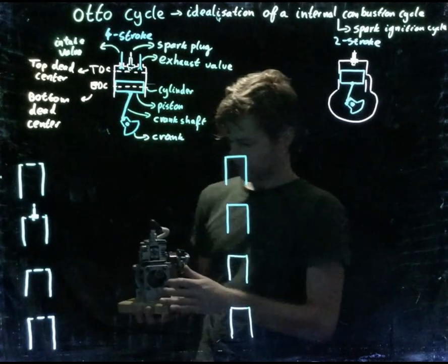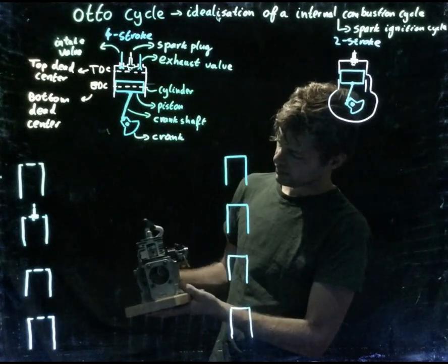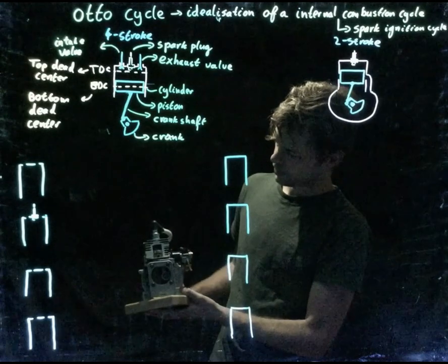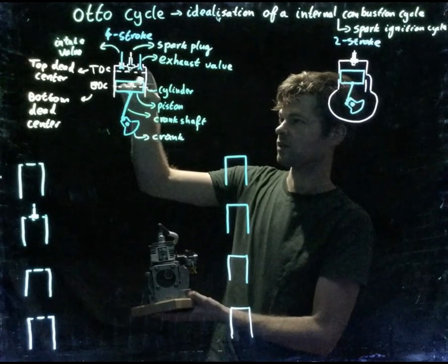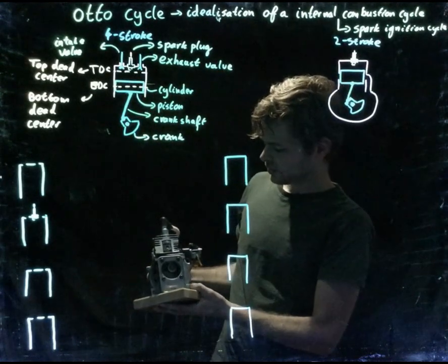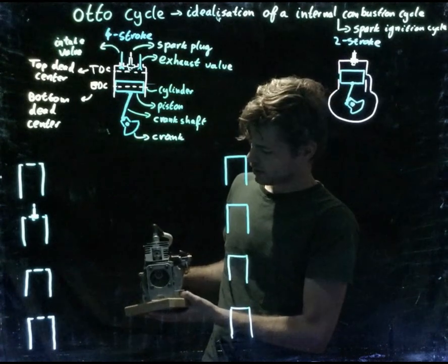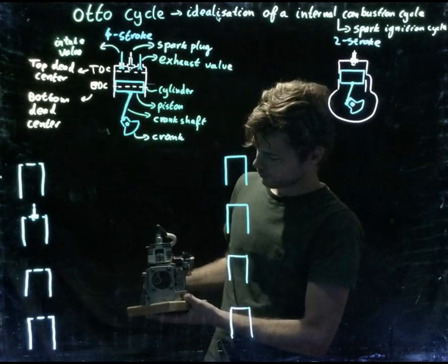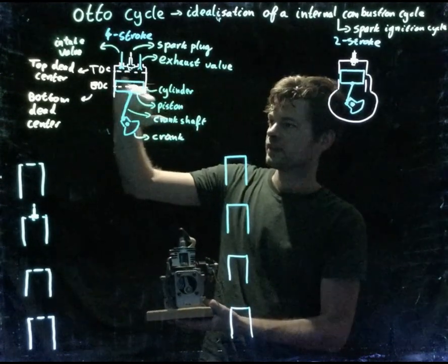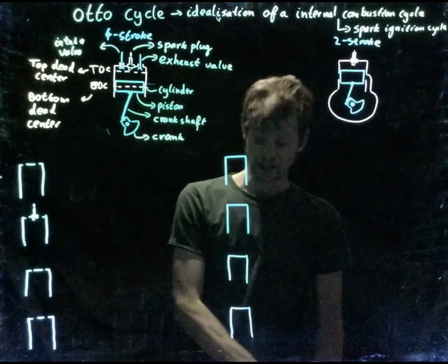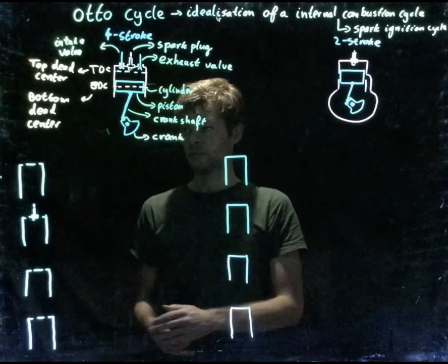I hope you can see it over there. When moving from the bottom to the top, the piston doesn't touch the top of the cylinder, but there's some room in between, and that room is actually used for combustion. And after that, it's pushed down again. So it remains for a split second at this top dead center, and at the bottom dead center as well.